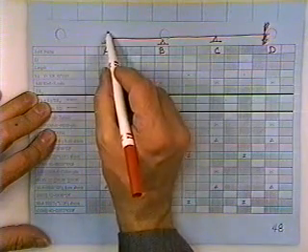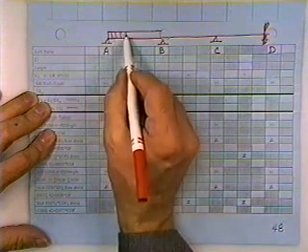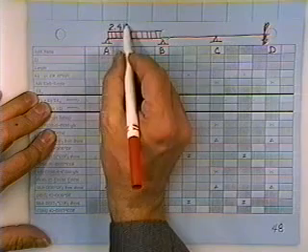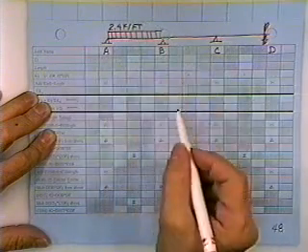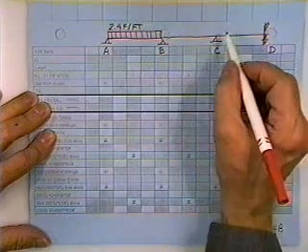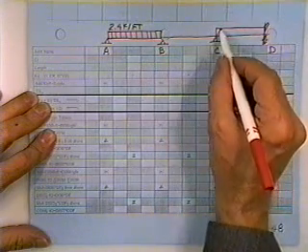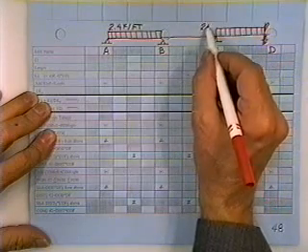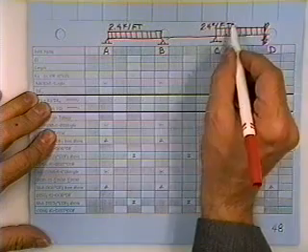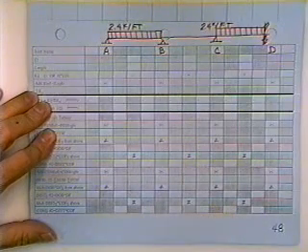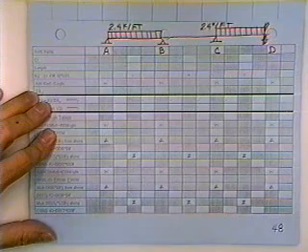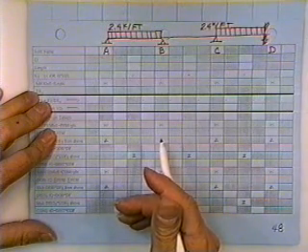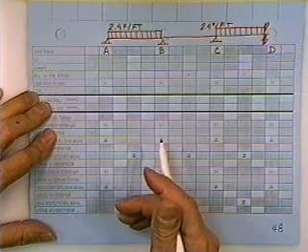I'm going to put a uniform load on this beam of 2.4 kips per foot from A to B, and I'm going to put another load, same magnitude, could be any magnitude, 2.4 kips per foot between C and D. Now that structure has moments inside of it which are not able to be solved by statics alone. There's too many reactions.